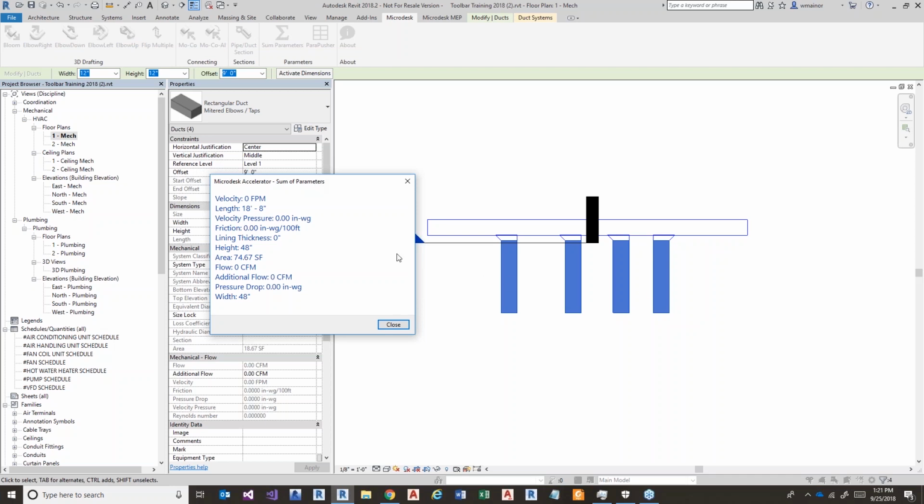The total length of the selected duct is 18 foot 8 inches. And the total area, or maybe the total width is kind of silly, but if you're using the tool for an intended purpose, you would know better what property you're trying to sum up than the tool would. The tool, in broad strokes, is just going to shoot from the hip and sum up every numerical parameter that's common to everything you've got selected.